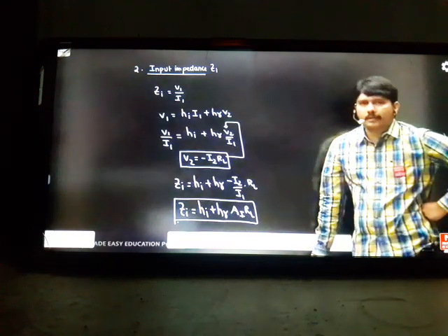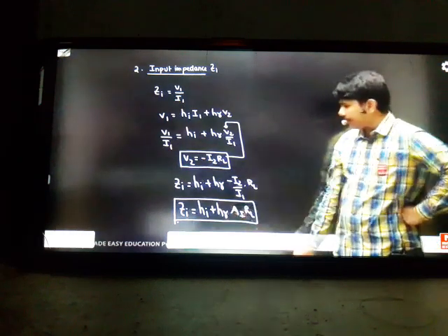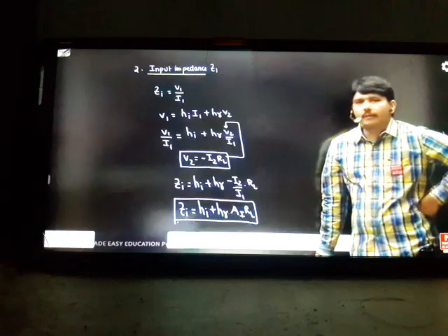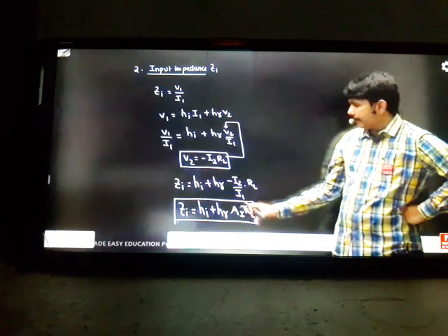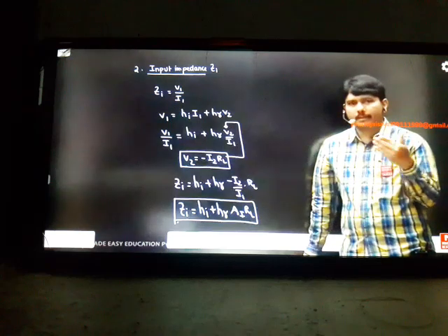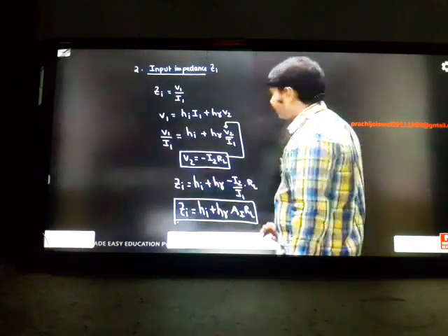You felt that previously hi is your input impedance, but in the exact model, it is not only hi, we have some extra quantities there. hr is there, current gain is there, load is there. It is depending on all these parameters. Okay? So then sir, why did you find current gain first? Current gain is a parameter which will influence your input impedance. So in the exact model there is an order of study. First the current gain I solved, next I came to input impedance. Okay? The next we have is concept number 3.